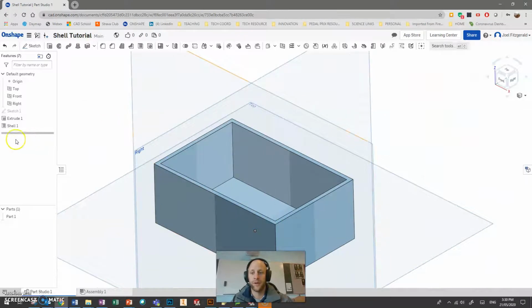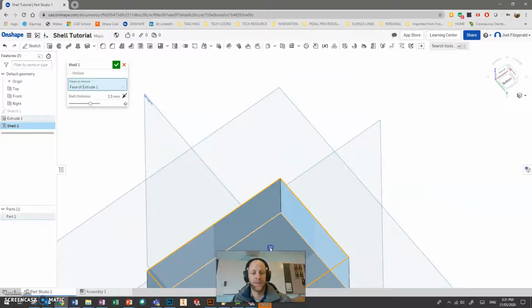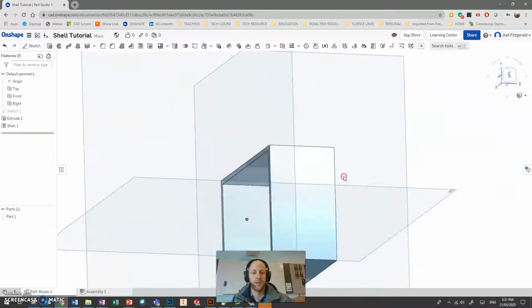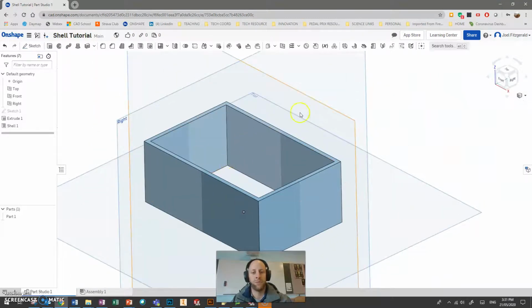This can be really cool if you're going to hollow, like maybe create a pipe. If you imagine creating a pipe, which is going to be your next tutorial, if you do 1 circle, so make it as a cylinder, you can then use the shell tool. And if you decide that you want to remove both faces, top and bottom, as 2 millimeters as the wall section of your part, there we go, cuts it through. So obviously this is a rectangle or a box, but if that was a pipe, a really fast way to get a nice consistent wall section.